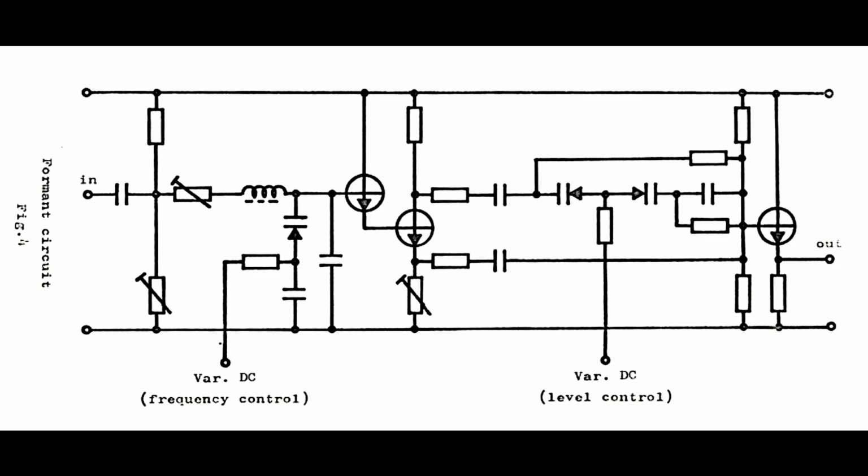So of course you can see when you have 0 voltage on your diodes, you have the highest capacitance, and then it is the same as the bottom capacitor. So that means the positive and the negative phase zeroes out, and then you have 0 output. So this is how they created a DC variable level control.